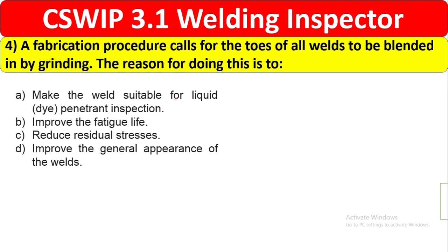Make the weld suitable for liquid penetrant inspection? No. We are not using it only for this. Definitely blending can help for liquid penetrant inspection, but this is not the right answer. Improve the fatigue life, reduce the residual stress.